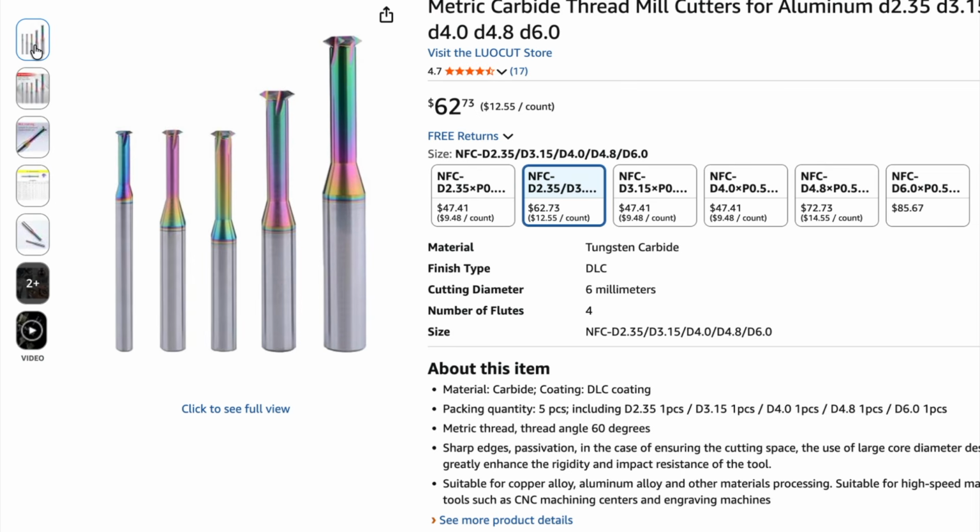It's not going to have enough torque to turn it. So thread mills will do a variety of thread diameters and thread pitches. Actually, theoretically, if the thread mill fits in the hole, it will do any diameter. But the pitch is determined by the geometry of the cutter on the end of the tool. So certain thread mills can't do certain thread pitches.